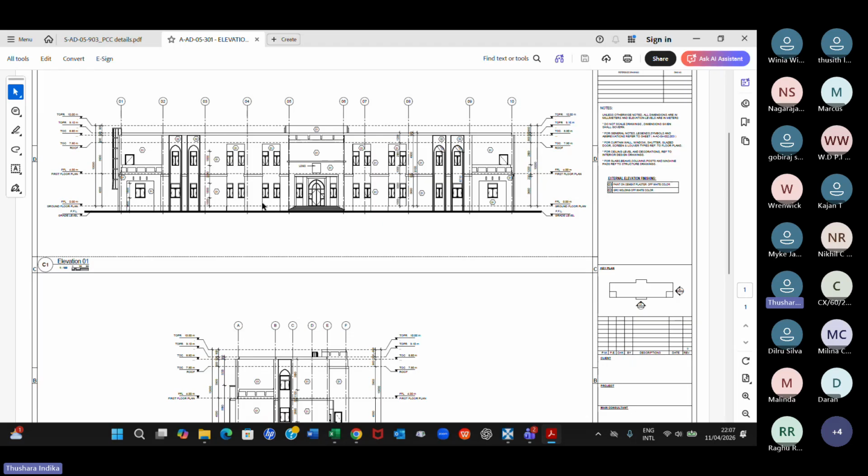So let's say you have about 3 or 4 thicknesses of a particular slab, right? So you have to create dimension groups. Let's say 200 millimeter thick slab, 250 millimeter thick slab. So likewise, you have to create dimension groups if you have to measure superstructure.